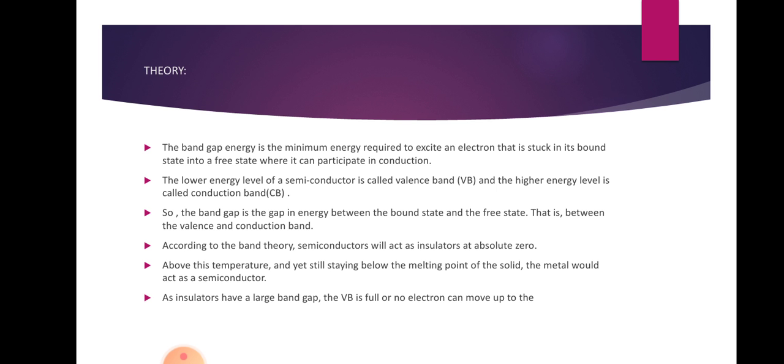Non-conductors means insulators. The band gap energy is the minimum energy that is required by the electron to move from its bound state into a free state where it can participate in conduction. The lower energy level of the semiconductor is known as the valence band, and the higher energy level is known as the conduction band, where the electrons will be free. So the gap in band gap is the gap in energy between the bound state, that is between the valence band and the free state. Free state means the conduction band.